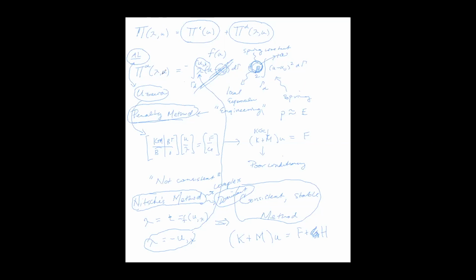And so the nice thing about the augmented Lagrangian is that it can accommodate basically any kind of linear or nonlinear constraint. Then you have a recipe for building the B matrices and adding the M matrix, and you can enforce any number of constraints.